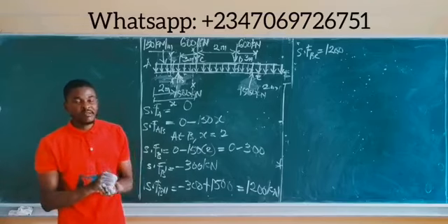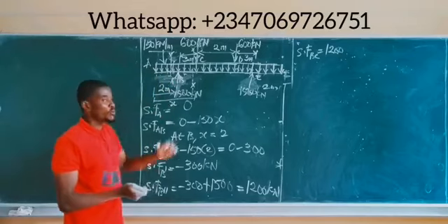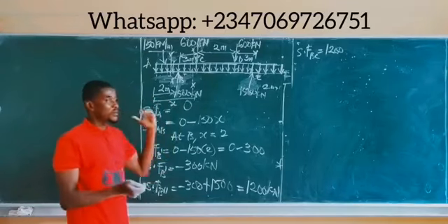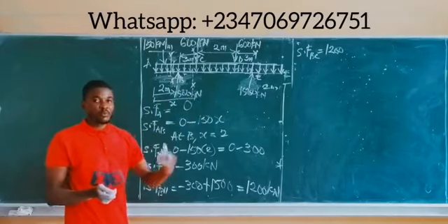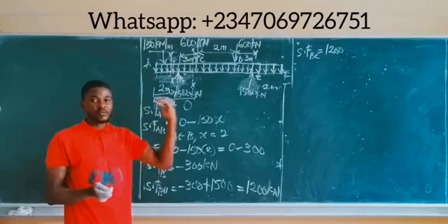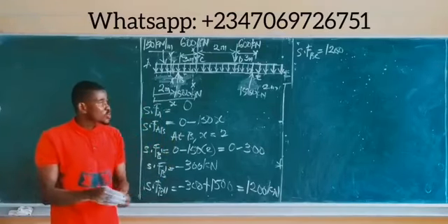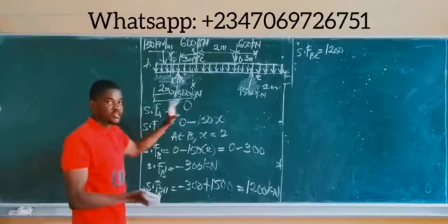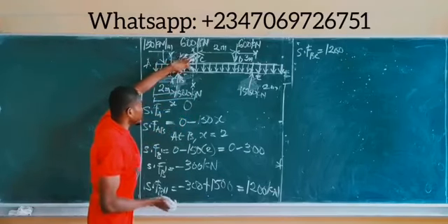In bending moment analysis, after you're done with one joint, let's say point A, and move to point B, we still have to consider all the forces behind point B to take moment about point B. If we move down to point C, we have to consider the forces behind point C, from A to B down to point C. But in shear force, it's stepwise at each joint. After point A, we move to point B. After point B, we go to point C. So we need to find the length of the UDL between point B and the point of section.